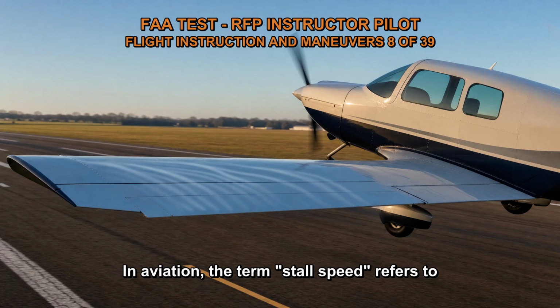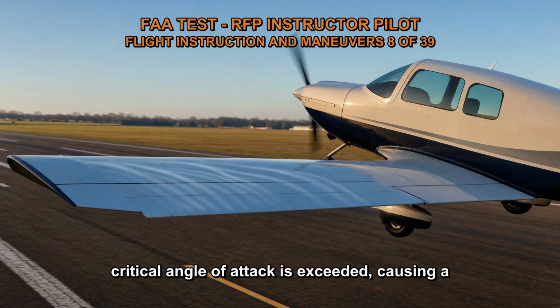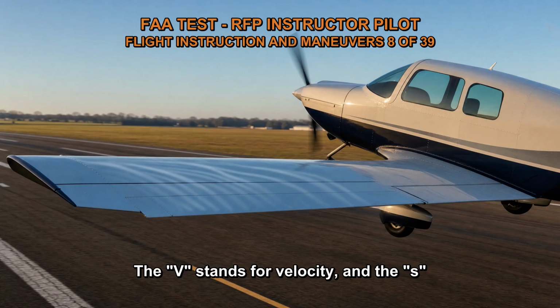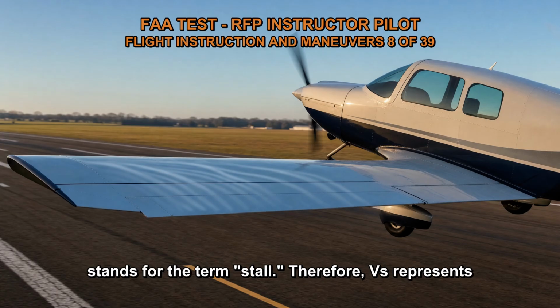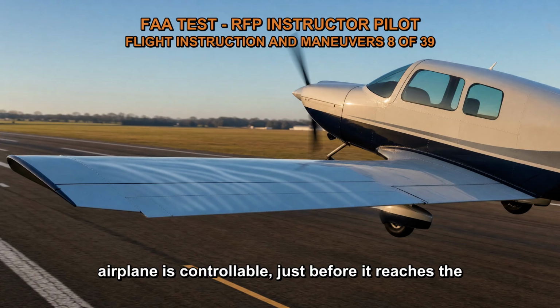In aviation, the term stall speed refers to the minimum speed at which an aircraft can maintain controlled flight. It is the speed at which the wing's critical angle of attack is exceeded, causing a loss of lift and a stall condition. The symbol used to represent the stall speed of an aircraft is Vs. The V stands for velocity, and the S stands for the term stall. Therefore, Vs represents the minimum steady flight speed at which the airplane is controllable just before it reaches the stall speed.